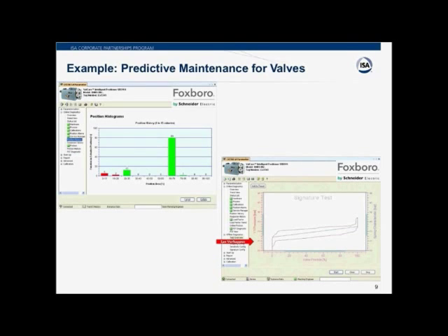One of the great things about the capability of this valve signature is that because we have the richness of effectively almost like a programming environment, we can automate a lot of these procedures so that we say, okay, signature test, and away it safely turns the device into an offline mode, runs the test, and then brings the device back to operational mode.